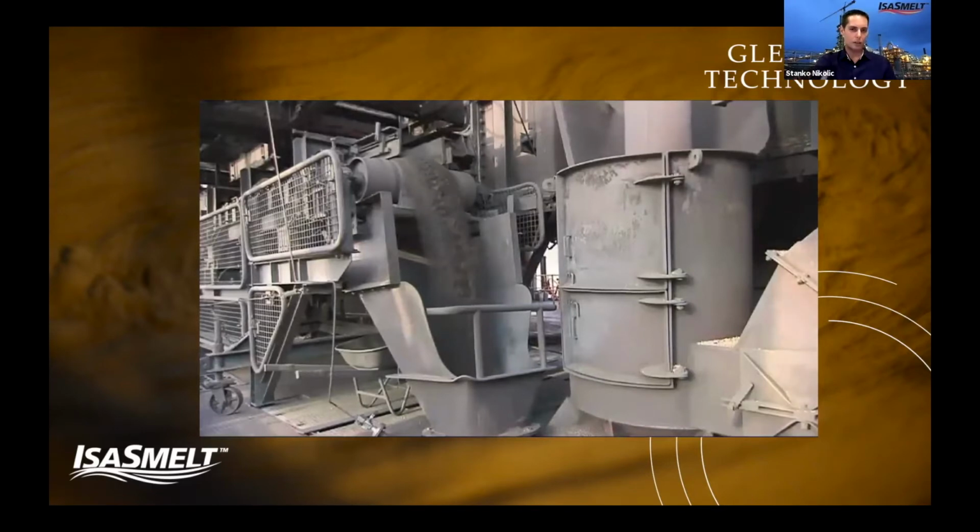So when we think about feed blending within a smelter, really it is about making sure that what we put in the front end, as you can see here, simple feed preparation that's been done, it's just a mixed concentrate that's still got some inherent moisture within it, mixed in with the fluxes and fuels and just dropped in through the roof port in the top of the furnace. We want to make sure that what's dropped in can be smelted to make the right products that we want in the furnace itself, so that then it can feed the subsequent parts of the smelter flow sheet.